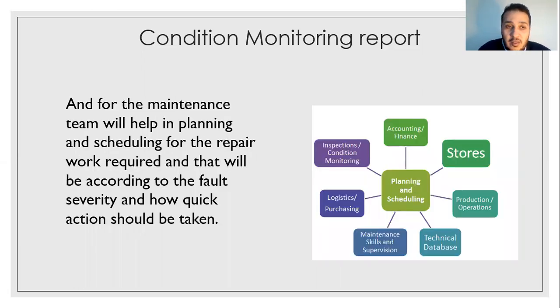And for the maintenance team, you will help them in planning. For example, if there is a gearbox failure and this gearbox needs to be replaced, and there is no spare gearbox in the store, you need to give them enough time with these fault stages. As a vibration analyst, you should understand the fault stages, and there will be a video about this, by the way, so you can explain to the maintenance team and recommend that within a couple of months this gearbox needs to be replaced, so that they have enough time to order a new gearbox, a new bearing, a new fan impeller or whatever.